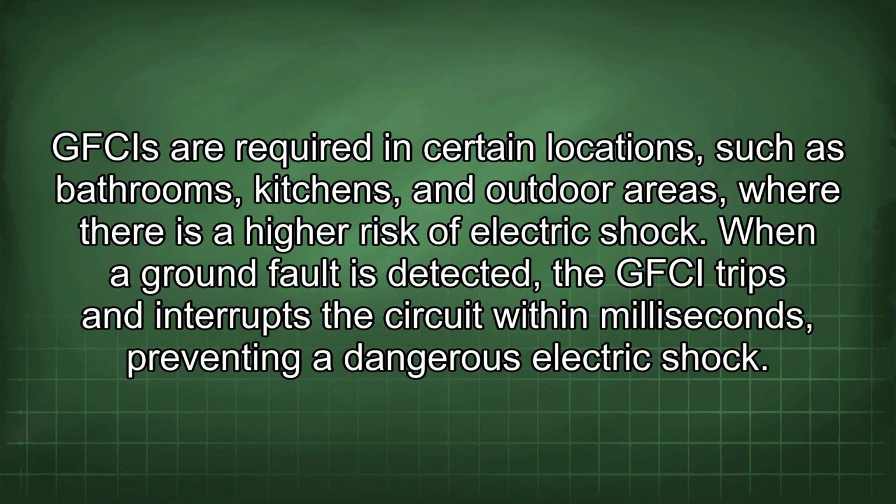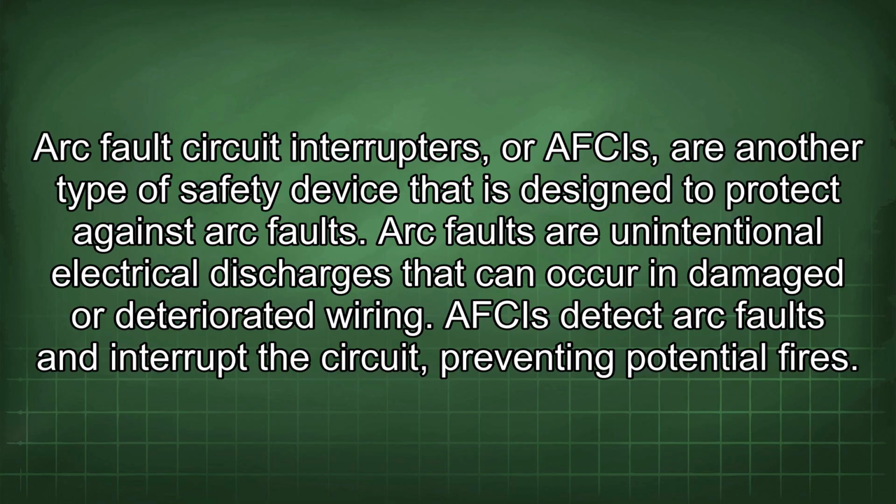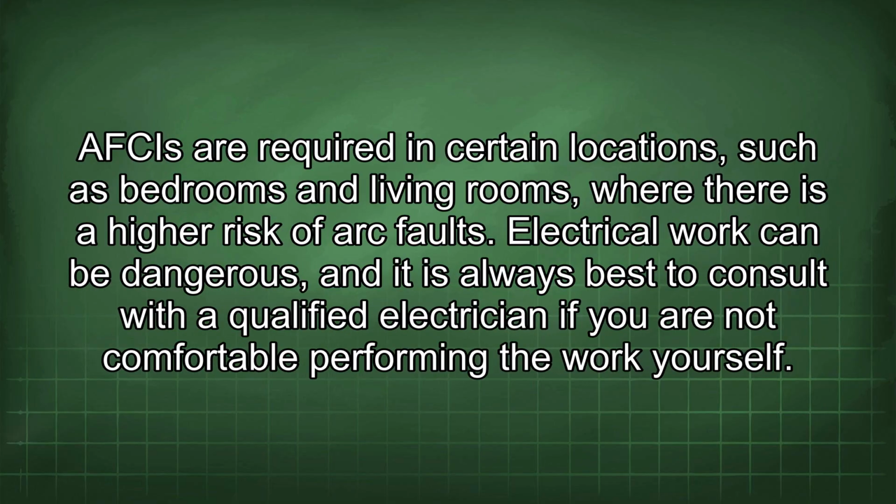electric shock. Arc fault circuit interrupters, or AFCIs, are another type of safety device that is designed to protect against arc faults. Arc faults are unintentional electrical discharges that can occur in damaged or deteriorated wiring. AFCIs detect arc faults and interrupt the circuit, preventing potential fires. AFCIs are required in certain locations, such as bedrooms and living rooms, where there is a higher risk of arc